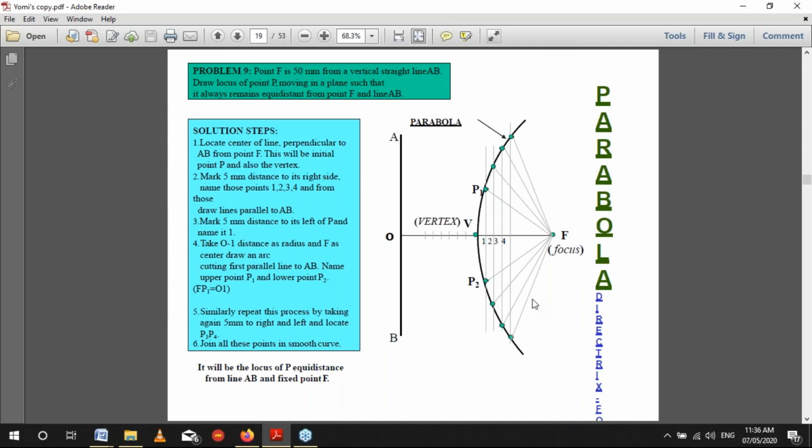Now, when generating a parabola, slide 20, I also want you to do it as part of the assignment. I've given about 4 assignments now, so please let's try and do them. Follow the steps for the focus, directrix or eccentricity method. Draw directrix AB and axis CC prime. Mark F on CC prime such that CF is 60 millimeters. Mark V at the midpoint of CF.